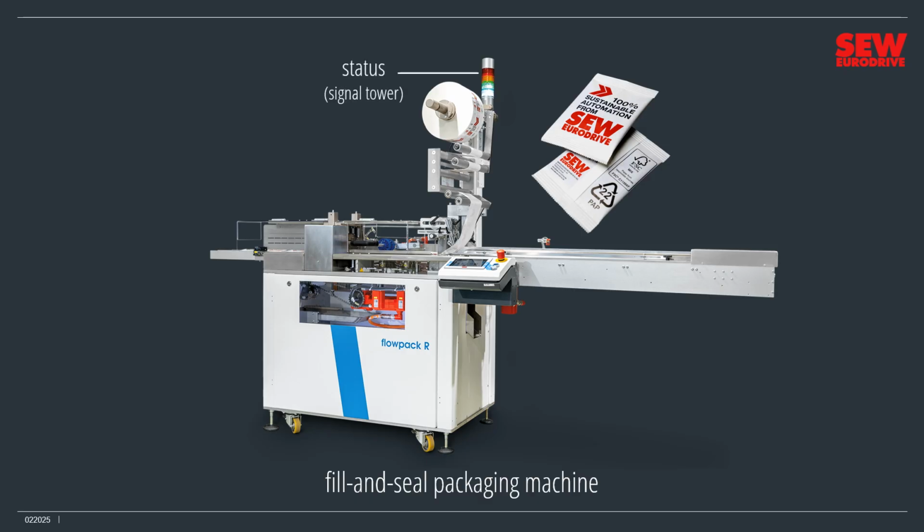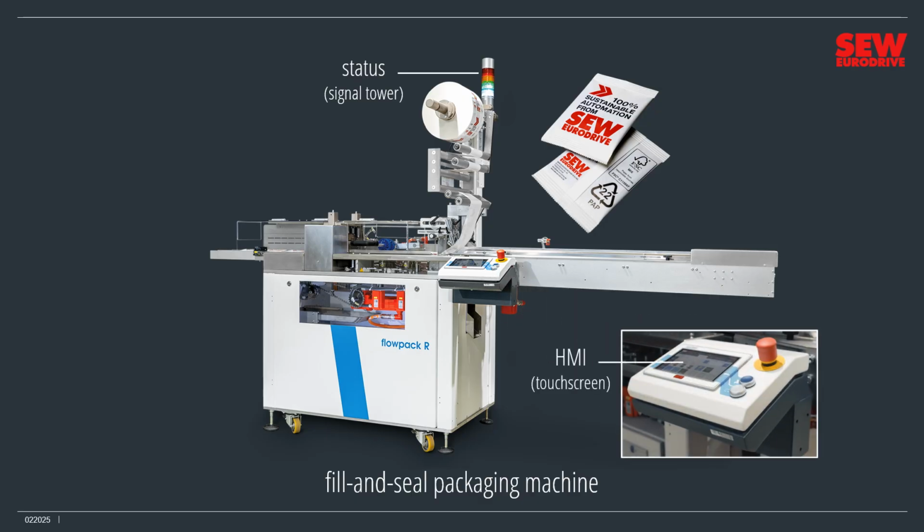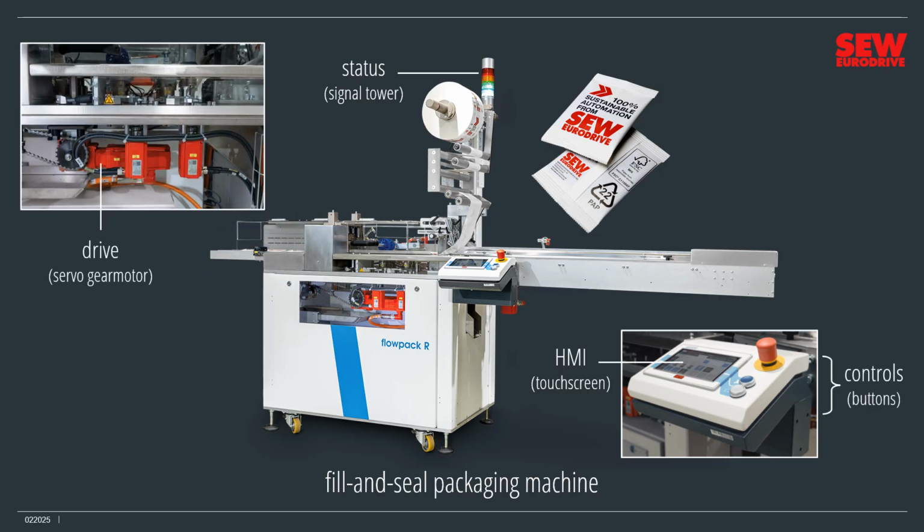The signal tower reports the machine's operational status at a glance. The touchscreen HMI, as well as several control buttons, give the operator easy control. A drive, in this case a servo gear motor, provides motion. Two stepper motor actuators perform the complex motions that fill and seal the packets.